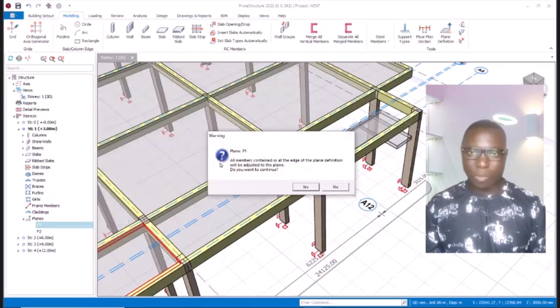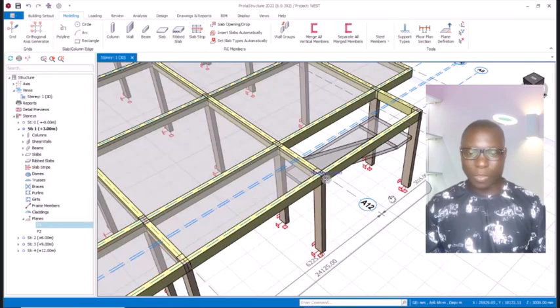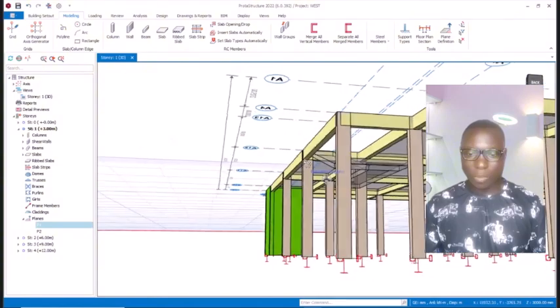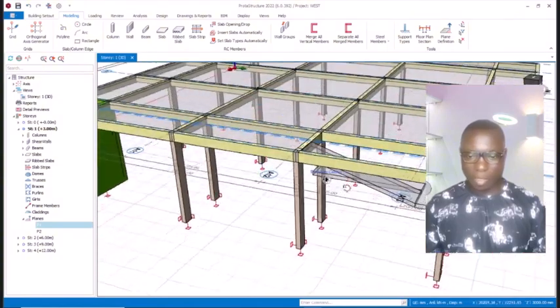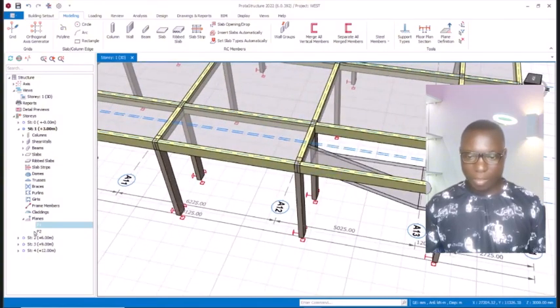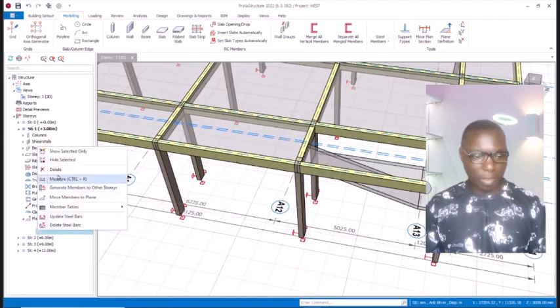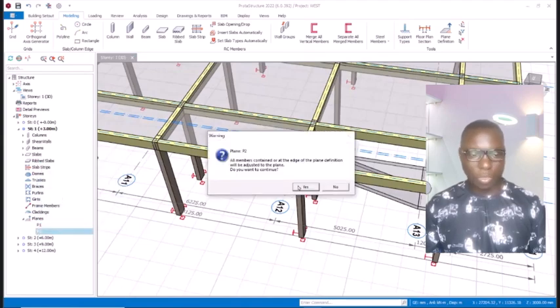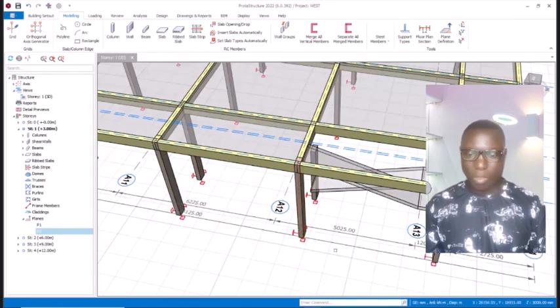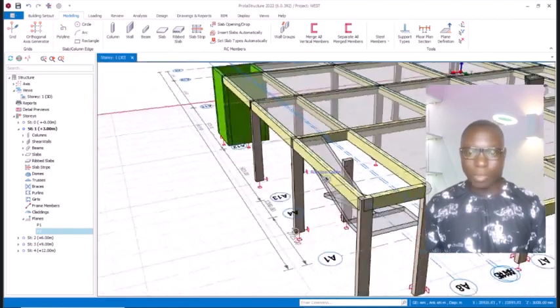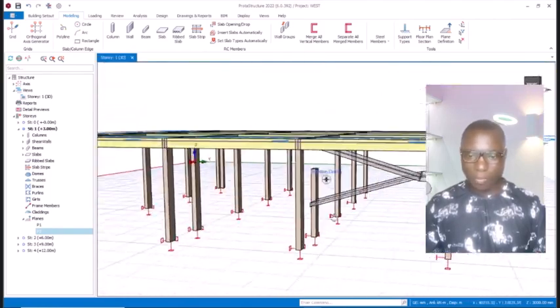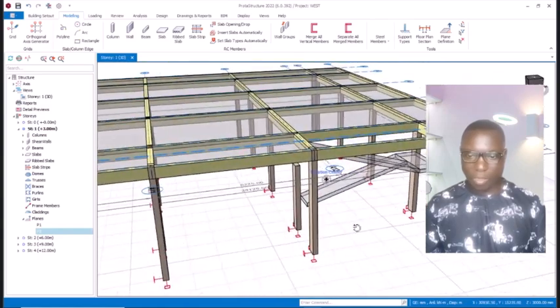I click that provisions and then yes options. You see what I've gotten right here. Okay, it's been moved successfully. The same thing applicable to plane 2. Right, move member to axis. You have this successfully. Unfortunately, you can see the column also moved, but that's not an issue.